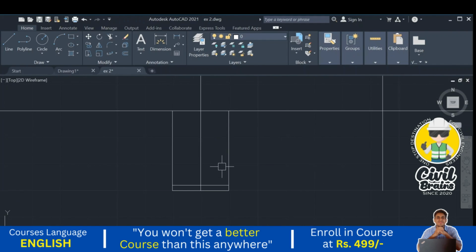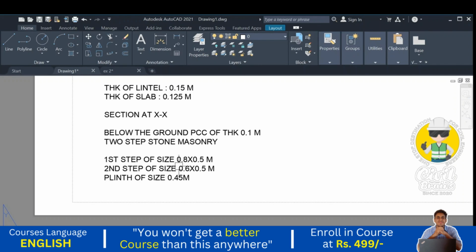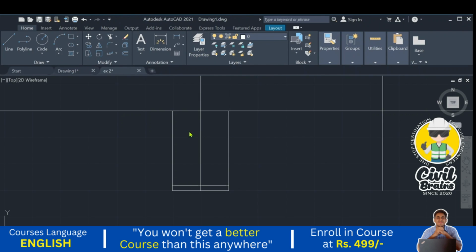Next, first step of the side stone masonry: 0.8 meter is the width, 0.5 meter is the height. So I just go to AutoCAD, offset 0.8 meter is the width. So this is the center line, 0.4, 0.4, press enter. And what is the height? Height is 0.5 from the PCC level. Correct.